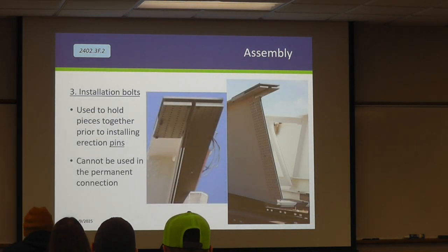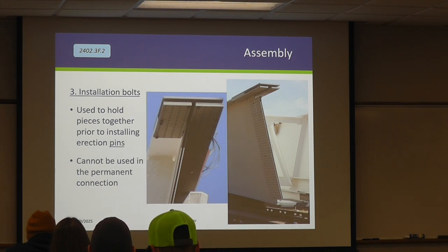Installation bolts are used to simply hold the pieces together, often for shipping, sometimes for setting things up in the air. They're not going to be incorporated into the permanent structure because we have no idea where they came from. There's no certs available for them. Oftentimes, if they're black bolts, they might not even be the right size. But we do allow them to use these to assist in their operation.